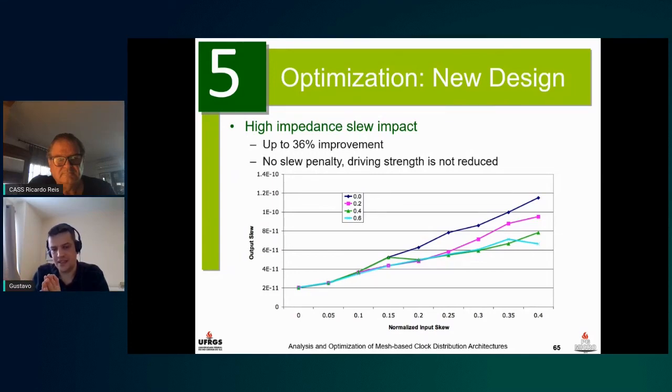The other thing is that the clock jitter actually has a very low frequency, in the sense that from cycle to cycle, the variation of the clock delay is not that much. It varies more over time. So the main problem with jitter is the cycle to cycle jitter, because that can impact the clock period.